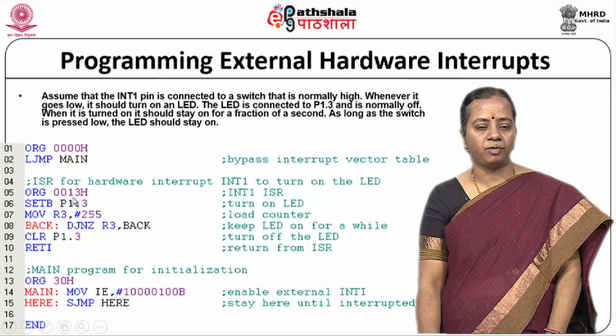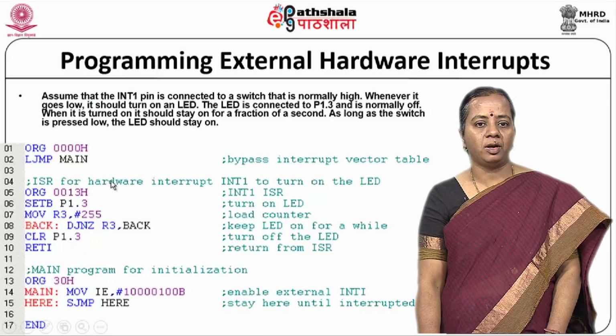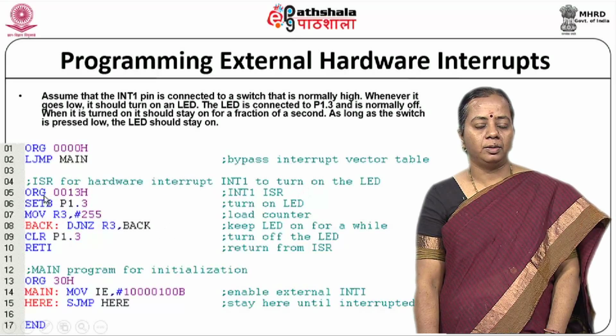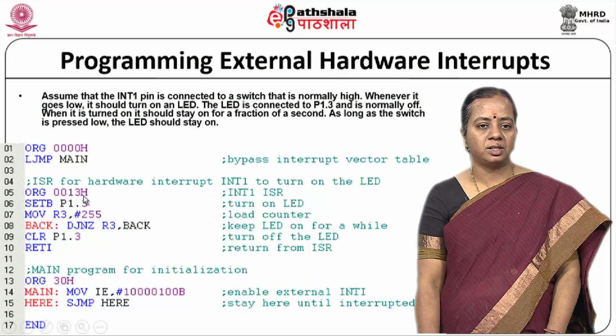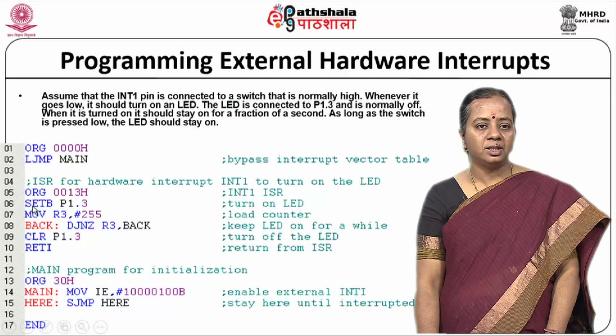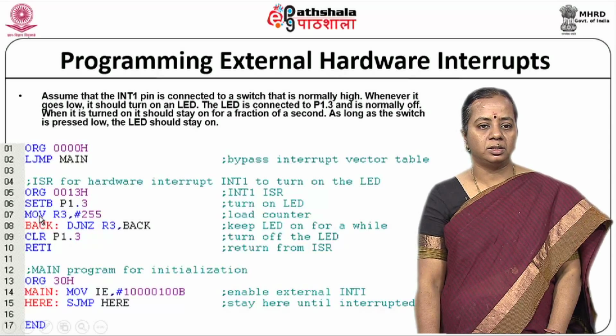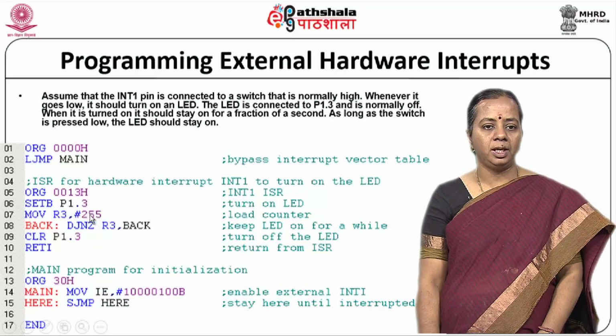Here it will be used for service routine. So, ISR for hardware interrupt INT1 is written at this particular location. So, ORG 0013H is written. The ORG says that the next location it has to start from is 0013. There it is written SETB P1.3.